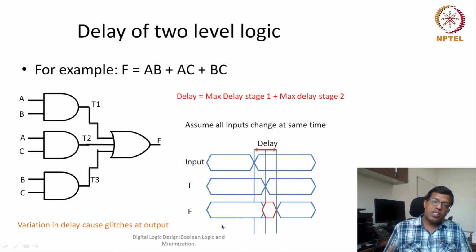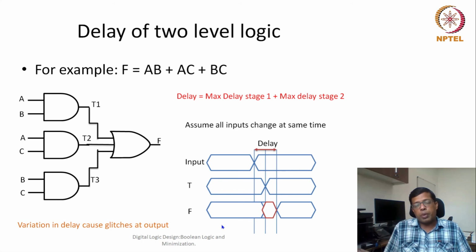So this also gives us one particular lesson: whatever is the delay of my whole expression, let's say the delay of my expression is equal to the maximum delay of stage 1 plus the maximum delay of stage 2. So what would happen if my input changes before this whole propagation delay of my expression?